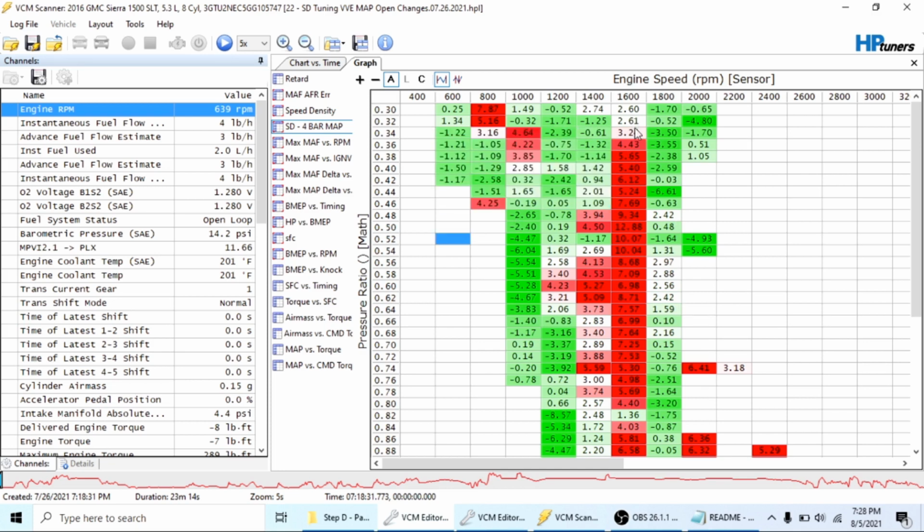But what's going on here is when I decelerate. I know for sure this 1600 to 1800 is my normal RPM range when I'm cruising on the highway, whether that's going 55, 60, all the way up to 70, 75. This is the range where the engine just likes to cruise, so it's where I'm going to get a lot more data points collected. And what I'll notice when I'm driving and logging is it might begin looking like this, and then as soon as I let my foot off the throttle, it'll start looking like that.